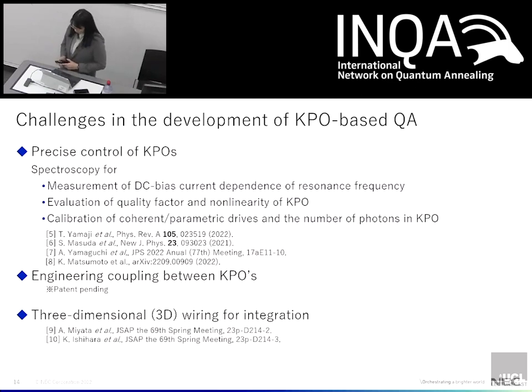And secondly, I will explain about the coupling between KPOs to make their network. I will show preliminary results of 2 and 4 KPOs. And finally, I will focus on the 3-dimensional wiring in order to access the individual KPOs in the integrated structure. We managed to input and read out signals with a 3D structure consisting of an interposer and socket. So I will introduce our structure and the result of the demonstration.